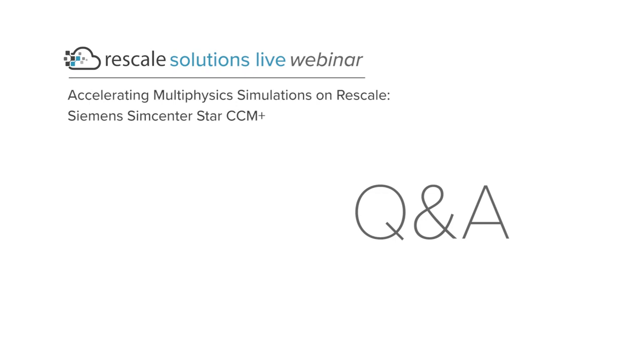Also, generally speaking, that's a very complex question, because it also depends on the physics you are studying. For instance, let's imagine that you have a simple flow, and these kinds of configurations scale very, very well, you know, linear scalability. But for instance, in Star CCM Plus, when we add, I don't know, a Lagrangian solver, then the scalability is not exactly linear, although the Lagrangian solver of Star CCM Plus scales very, very well.